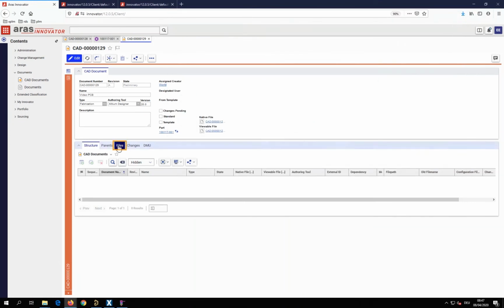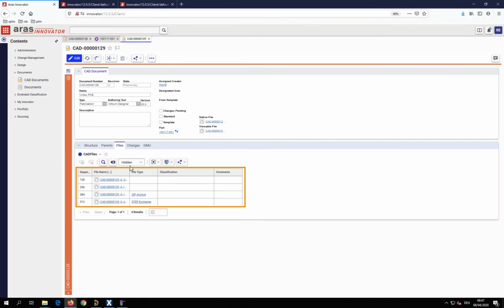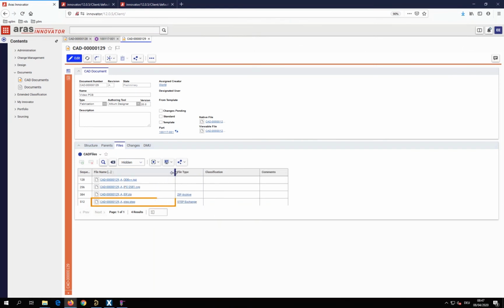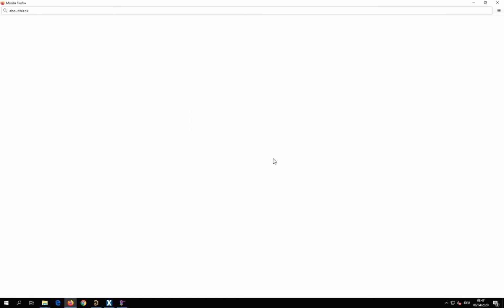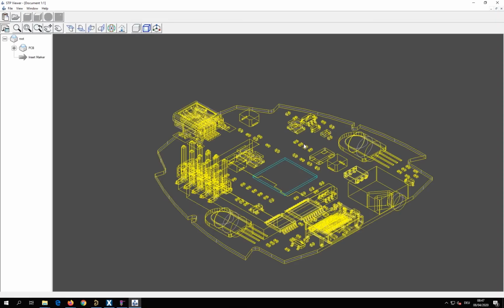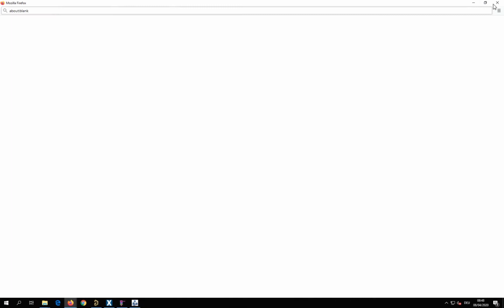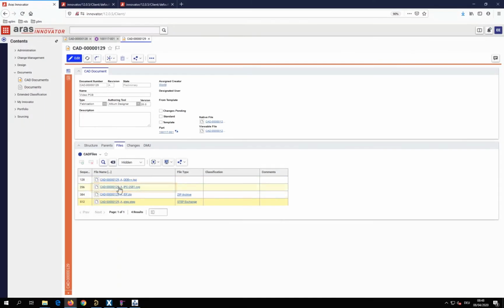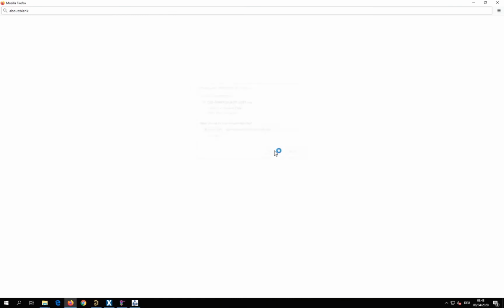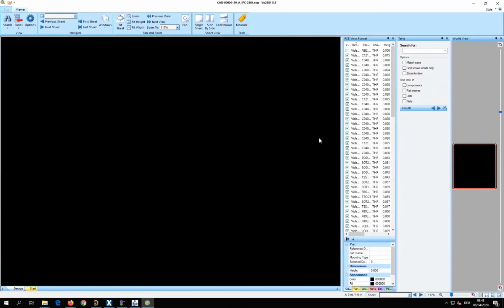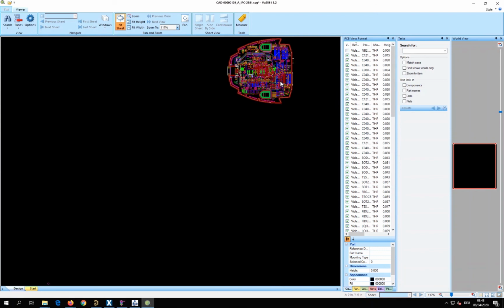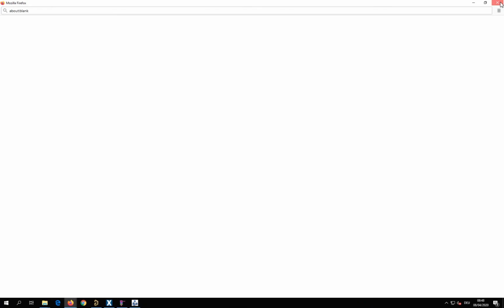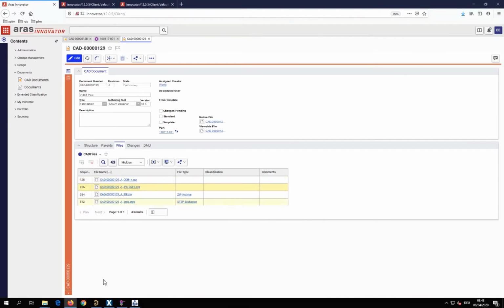For collaboration purposes, for example, a collision checking against the enclosure, often a 3D model of the printed circuit board is needed. This viewer shows the step model of the full assembly. The manufacturer's data format, IPC2581, an alternative to Gerber, ensures cross-company and cross-process CAD flow from the PCB design tool to the production with just a single data format.